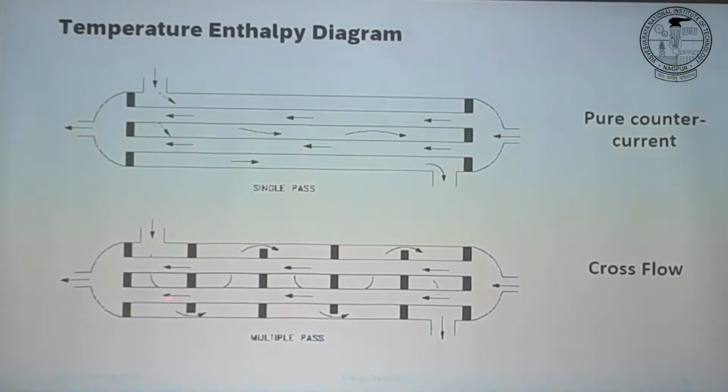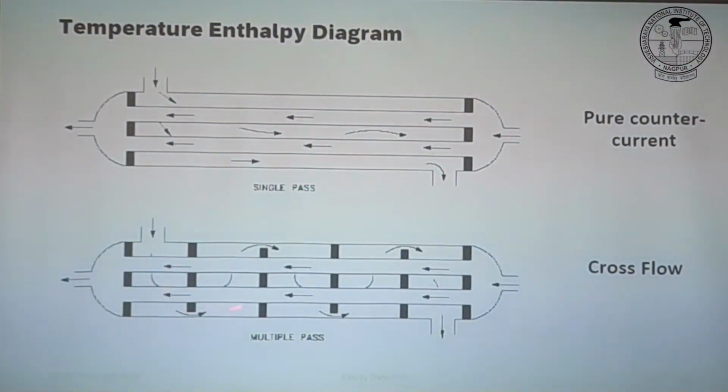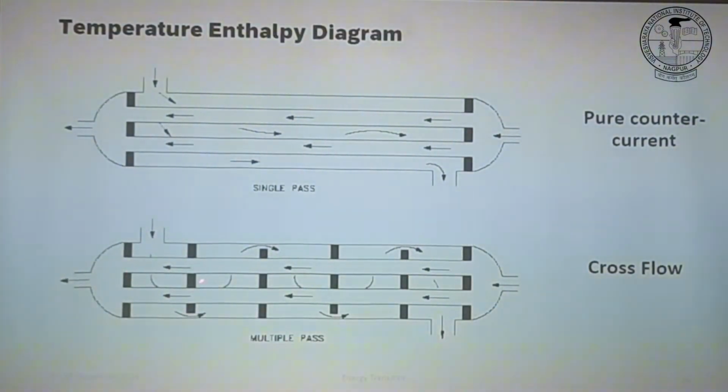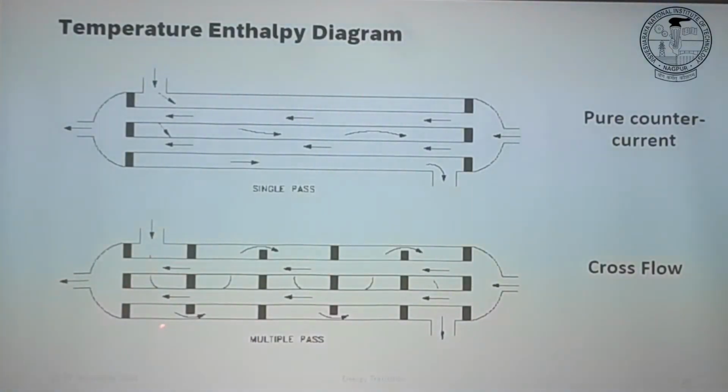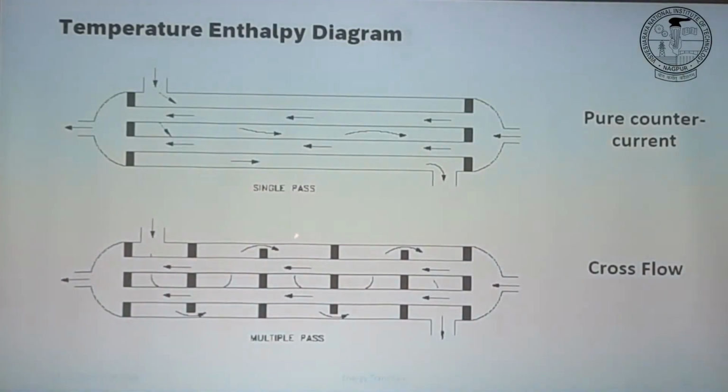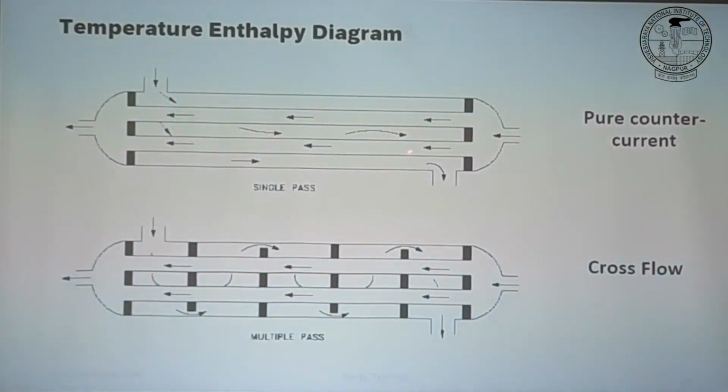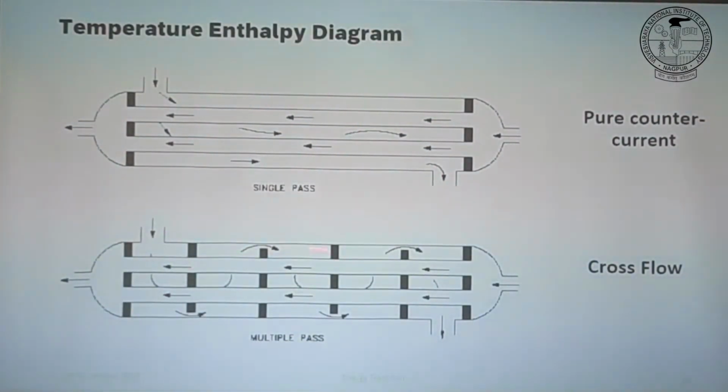This multiple LMTD. So ideally what you will do, your Q equals UA LMTD equation here, calculate your LMTD for only this region, temperature here, temperature here, temperature here, temperature here. That's even cross current. So what I want to say, this is your pure co-current, counter current. But in a real exchanger, you have in some region co-current, some region counter current, some region cross flow. Okay. So it's a kind of mixed flow.